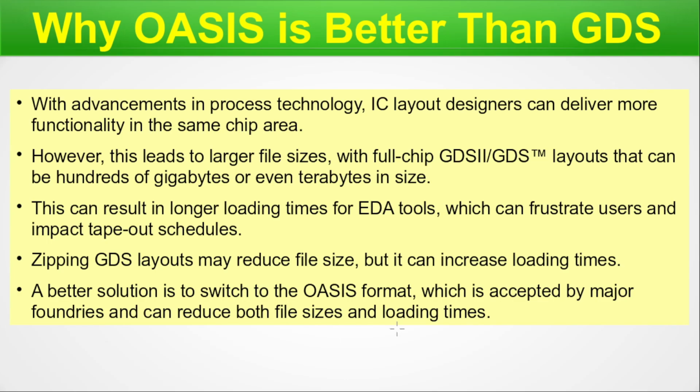Now let's come back to this point. What happens is that the file is loaded on a machine, but that machine is not the physical machine that you are using. It's a remote machine that you have invoked through the LSF or the UGE command, and that machine has a large RAM and all these things. These machines are not in abundant quantity in any design house, so they will be in a very restricted quantity. When you are booking and using a machine dedicatedly with the large RAM and the disk area, you are actually at that time depriving others of using that particular machine.